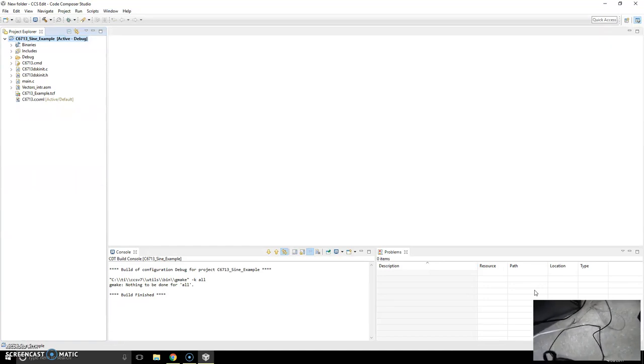the mic in jack on your computer, and then this line in jack should go to the headphone jack on your computer. So just to repeat, the headphone jack on the computer should go to the line in on the board. The headphone jack on the board should go to the mic in on the computer. Okay, so that's this blue line. Alright, so it's imperative that you get that correct.